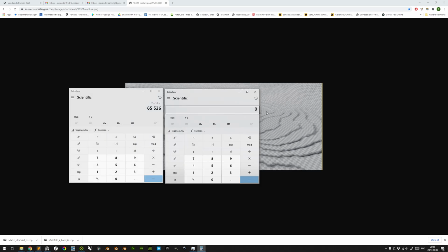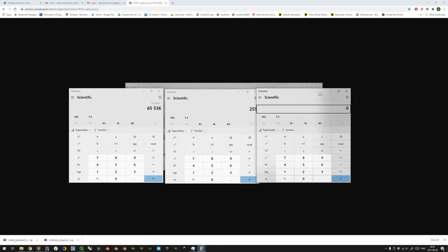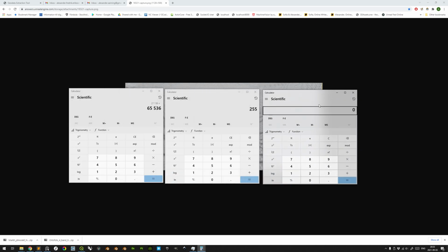With the previous example of the 255 meter high landscape with the 1 meter terraces, due to the constraints of the 8-bit format, a change from 8-bit to 16-bit would reduce the increments from 1 meter to something like 0.003898, or about 4 millimeters. This is of course depending on the height of the given landscape.